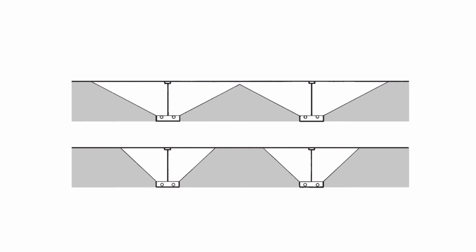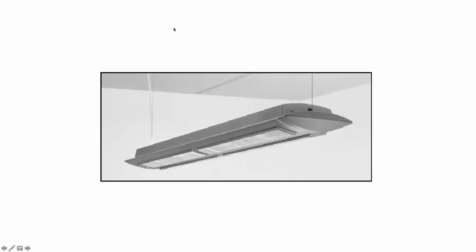So when you look at the suspended luminaires, and these are uplights entirely, they should have a spacing such that you don't get dark spots in the middle. And again, the layout of your space is up to you, so you'll want to determine what's going to look good in your space. For example, are there rows of seating that you want to align with? Then maybe you want to align these with that. So then you purchase a fixture which has the right light distribution for your use.